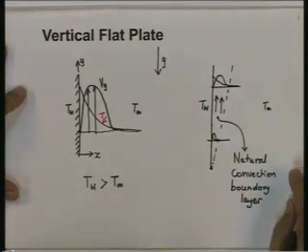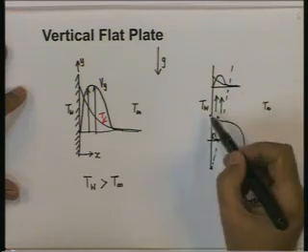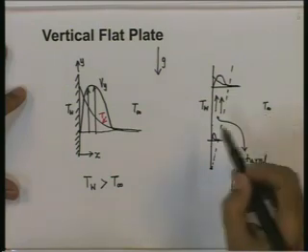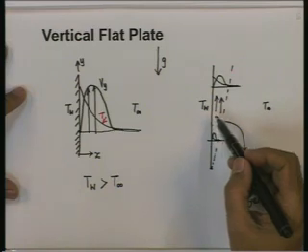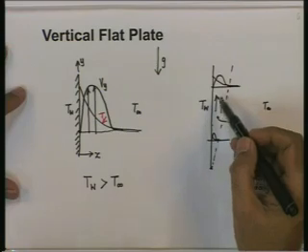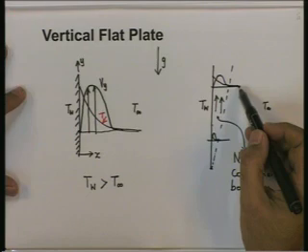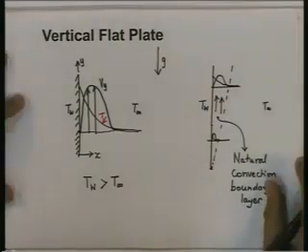It is similar to the forced convection boundary layer, but with the difference that this is the zone in which the temperature is significantly different from the free stream temperature. The effect of the wall is seen. Because the temperature is different, the density is different. Because of density difference, there are buoyancy forces which cause local flow of fluid. In the free stream, the Vy will tend to be 0, because the bulk is not moving at all. It is a natural convection situation.